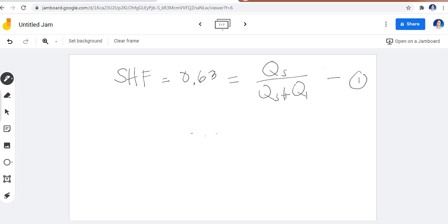Now we can determine the dew point temperature, and that would be your effective coil temperature. I mentioned during the discussion that the dew point temperature is also your effective coil temperature. How will you find it? From the psychrometric chart, you can read this to be more or less equal to 10.3 degrees Celsius.